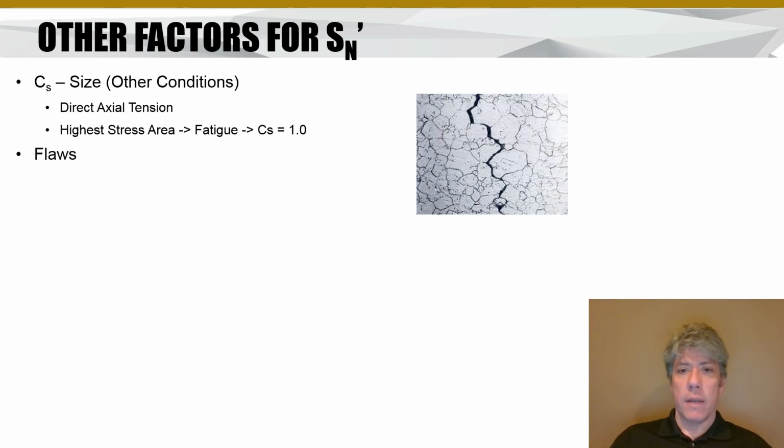And if you can't x-ray it and measure them and know what those flaws are and compensate for them, then you should probably increase your safety factor and derate your endurance strength quite a bit, or maybe even test some samples and try to get a good handle on your average and high and low, your range and variation of endurance strengths would be given that casting process and material and so forth. So flaws can cause a lot of problems in material and reduce the endurance strength.